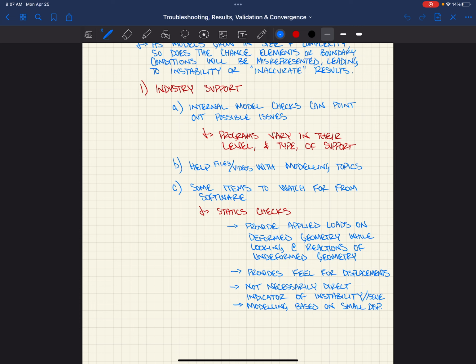Moments and forces. So in this case, if I'm in the dead load case, and I'm in the Y forces, maybe we'll start with X forces, 0, 0. It's a very quick way of coming through here and looking at a model and saying, all right, if I have just vertical dead load, then my assumption is that I shouldn't have any lateral forces. And so if all my forces are sourced in the Y direction, then I shouldn't have any forces in that direction.